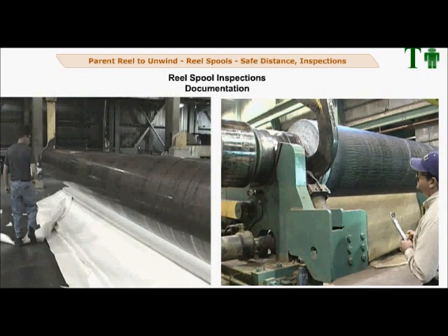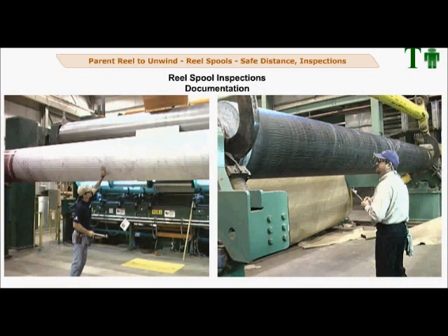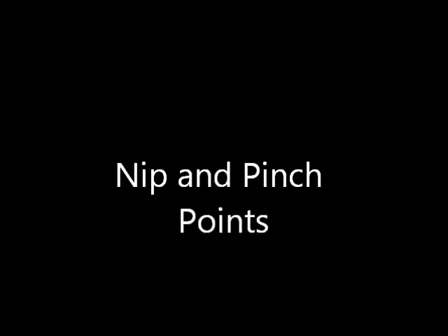There should be annual reel spool inspections. Reel spools have the potential to crack over time. These detectable and preventable failures are usually pretty catastrophic in nature. Each mill should have a detailed and documented regular scheduled, possibly annual, inspection process for each spool that includes the spool journals.